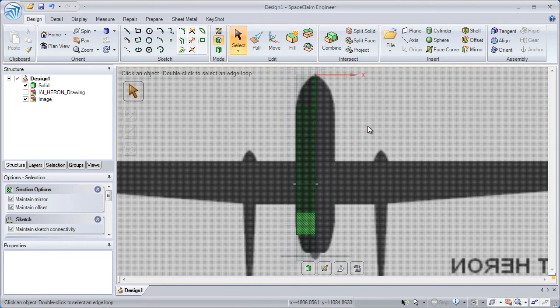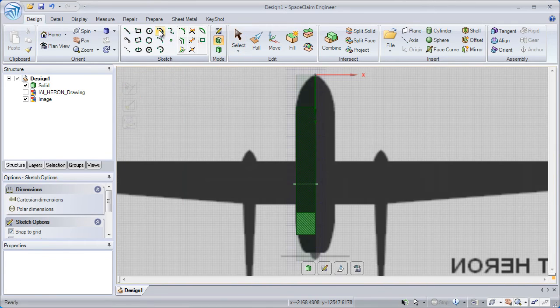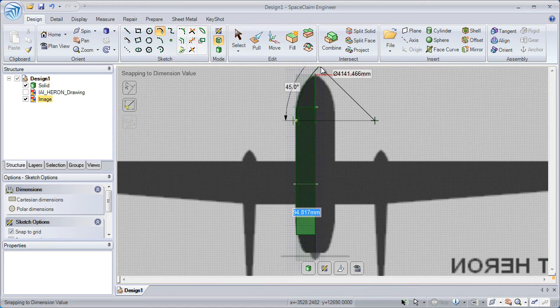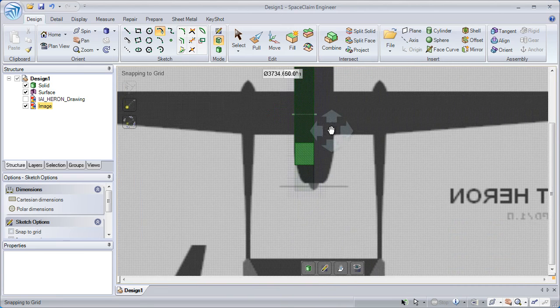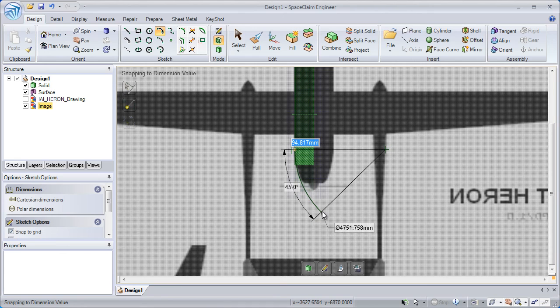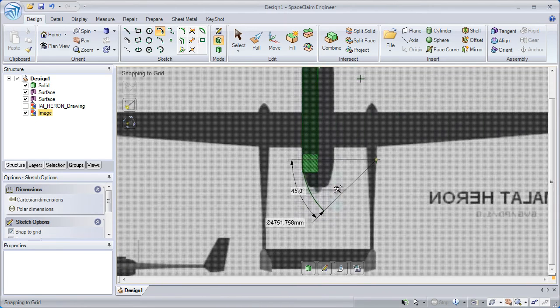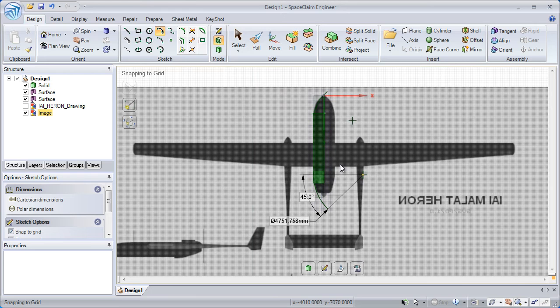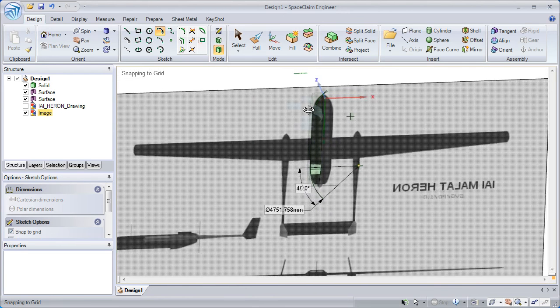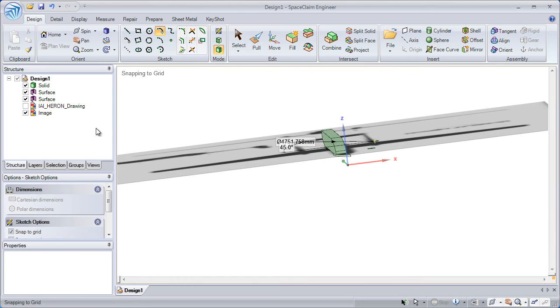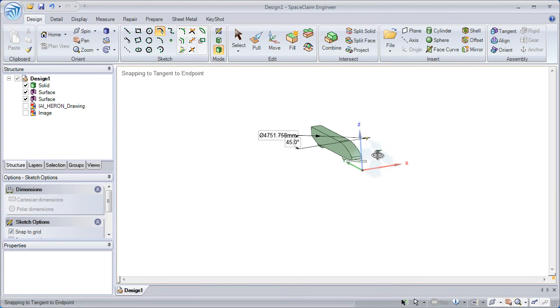We'll zoom in and use those same sketch tools to further shape our model to the image. Here I'll snap to the edge, but notice for the second click, I'm just clicking in white space. Here we'll use a different procedure for reshaping this model. So now that we have the contours sketched out, let's switch back to 3D mode and go ahead and hide this image.